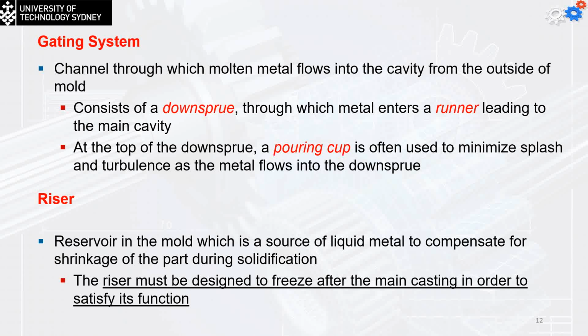The riser is a reservoir in the mold which is going to be a source of the liquid metal to compensate for the shrinkage of the part during the solidification. And this riser must be designed to freeze after the main casting in order to satisfy the function.